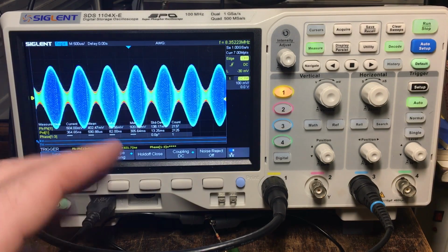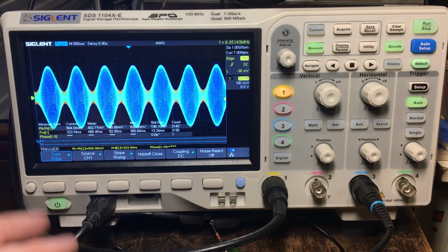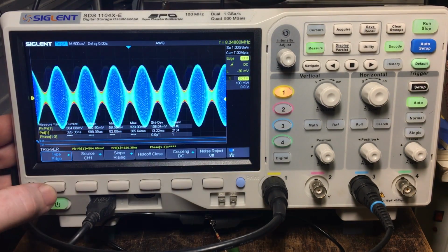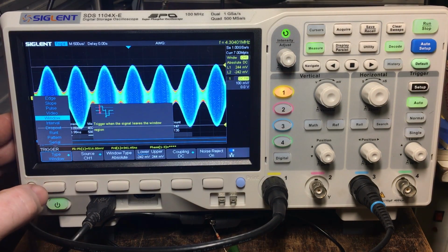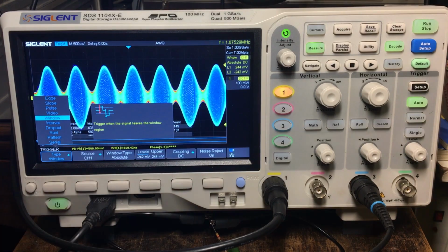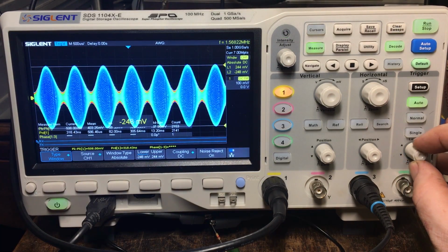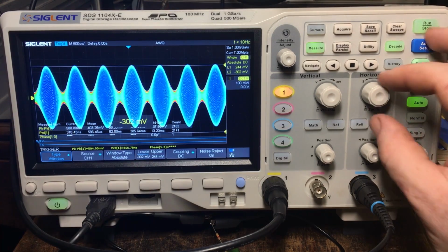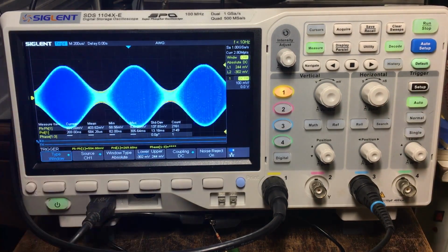Right, so I'm just going to do some sample testing on this. So this is a 10 MHz signal with 70% AM modulation, which is always something that's just hard to lock onto. I've already preset some triggers on this, so I've already set up a window trigger, which is a fairly stable way of actually detecting this one. So I'm playing around with these trigger levels on here, not going too far. I can see it's pretty stable there. No, it's not too bad.